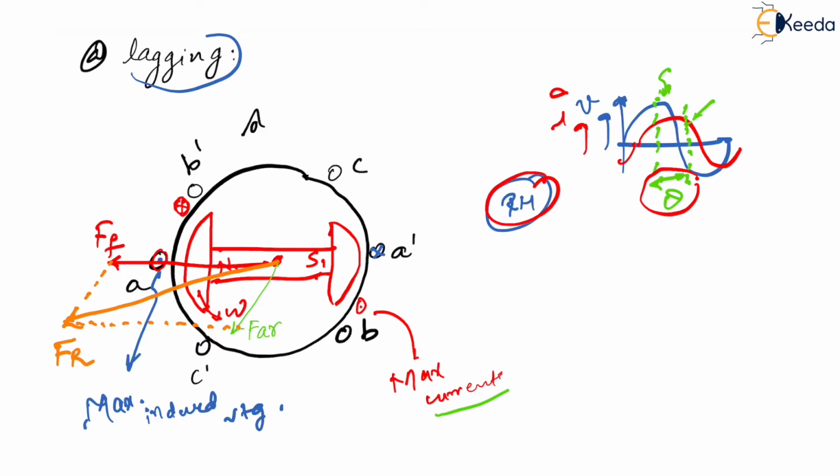Yes, very simple. Since it is entering into the stator here, this becomes the south pole of the resultant and this becomes the north pole of the resultant, exactly diametrically opposite to each other. Now what do we have next? This north pole and the south pole of the resultant will get attracted to each other, which means there will be torque produced in the same direction. Now torque and omega are both in the anti-clockwise direction, and this is what we need.